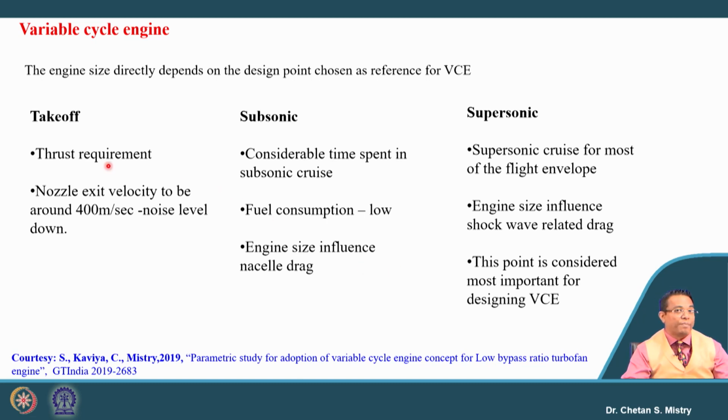Say takeoff, where the major focus is on thrust requirement, and we are looking for our exit velocity to be in the range of 400 meters per second. We are focusing on noise level, so we want to suppress the noise. At the same time, what is our requirement? We are looking for a higher amount of thrust.